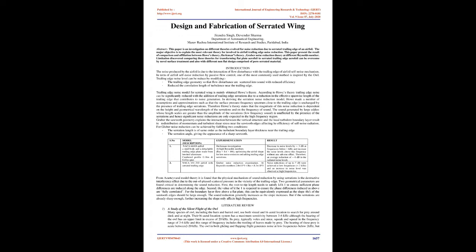Introduction. The noise produced by the airfoil is due to the interaction of flow disturbance with the trailing edge of the airfoil, the self-noise mechanism. In terms of airfoil self-noise reduction by passive flow control, one of the most commonly used methods is inspired by the owl. Trailing edge noise level can be reduced by modifying the trailing edge geometries so that flow disturbances are scattered into sound with reduced efficiency, and by reducing the correlation length of turbulence near the trailing edge.